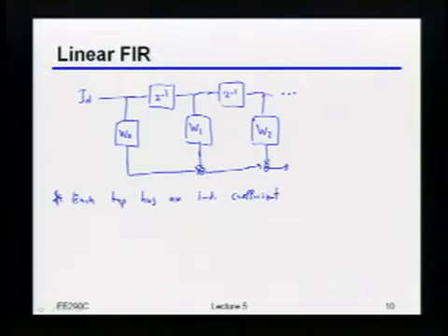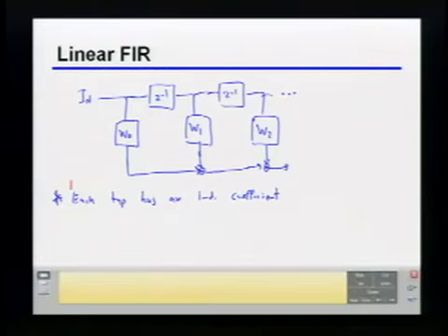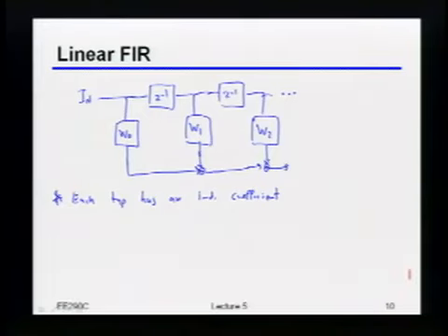So that just means that it's slightly more flexible, or perhaps even a lot more flexible depending upon how many taps you have, of course, in terms of trying to create these weird-looking shapes. Because by futzing with a combination of these 3 taps, you can create some shape that looks very strange versus what you could do with a straightforward continuous time filter like we had in the previous example. That's really the biggest differentiation there. The other thing to point out is that this is usually done at the transmitter.